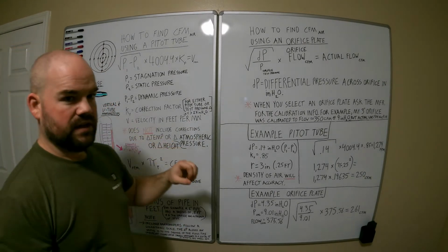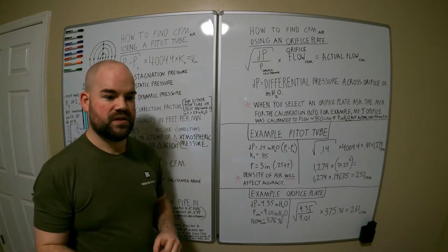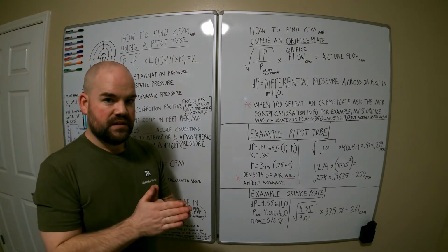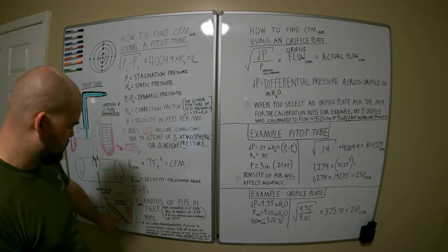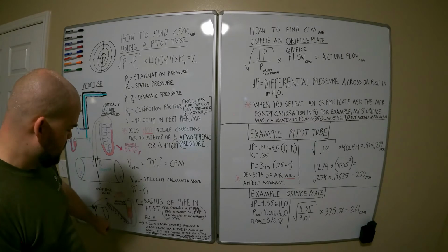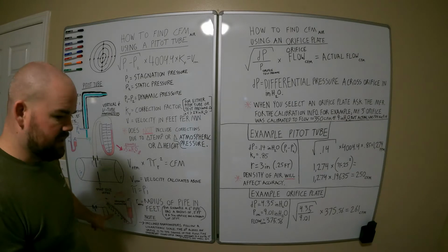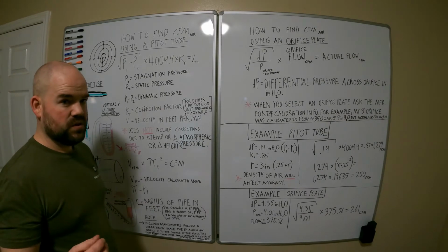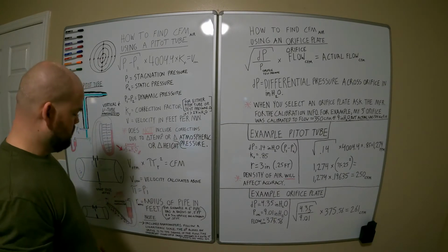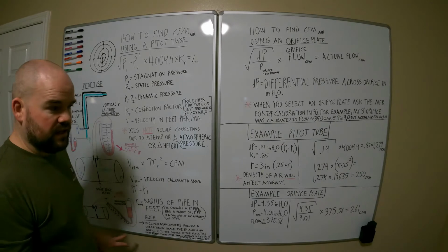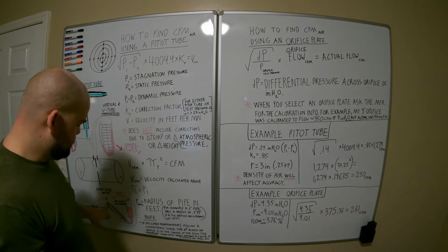Anyway, the reason why an SF600 bench uses different scales is because you want to see the flow at 60% or greater. Because as I described, the scale gets larger and larger, so it's easier to see the small changes. If you're flowing a cylinder head on an SF600 bench at a 3 inch orifice, but you're only flowing at 200 or 300 thousandths lift, and it's only flowing 150 to 200 CFM, then you're going to want to be at the smaller scale, and it's going to have a higher differential pressure at that scale range, and that's going to get you down in here.